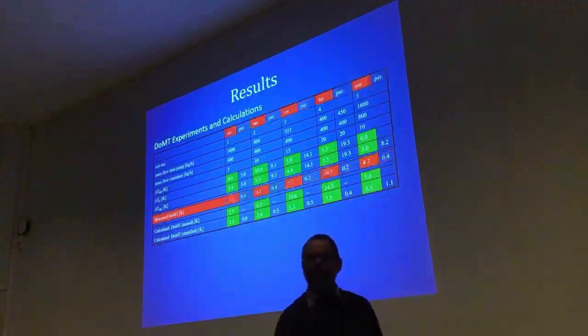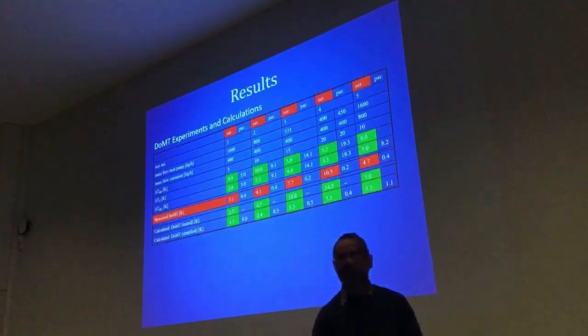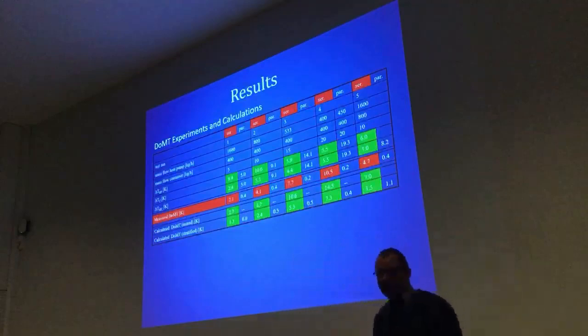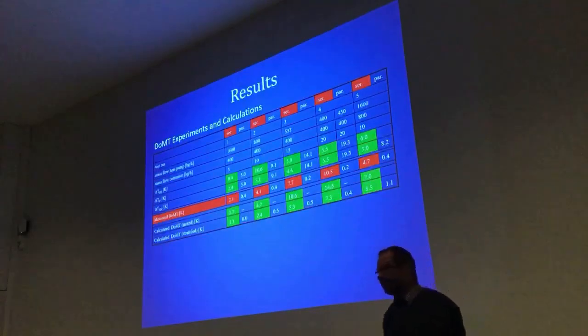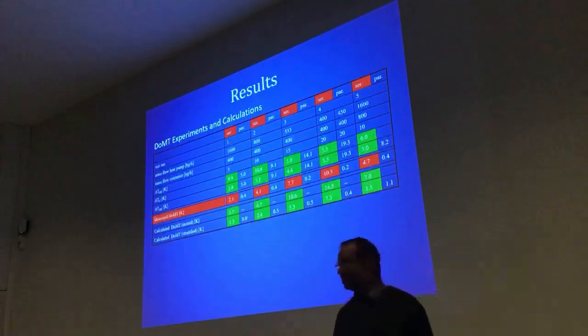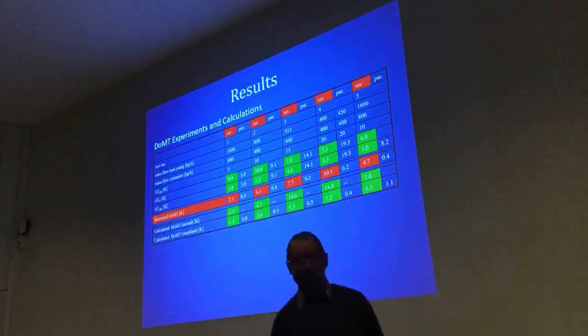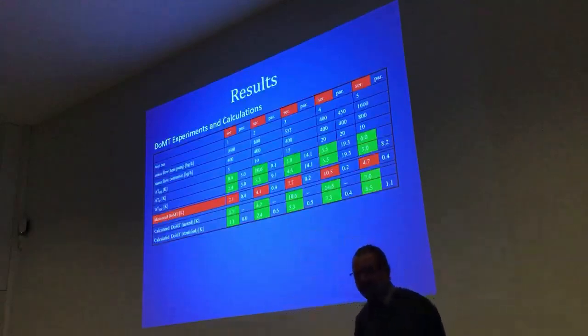In case of serial tank integration, the drop of mean temperature was much higher. It varied between 2.1 and 10.5 degrees Celsius. Have in mind, 1 degree higher temperature losses means 3% lower efficiency. So if you have temperature losses of 10 degrees, that means 30% efficiency losses. That's really amazing.